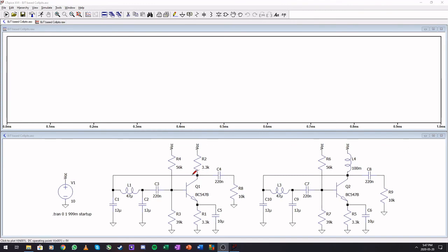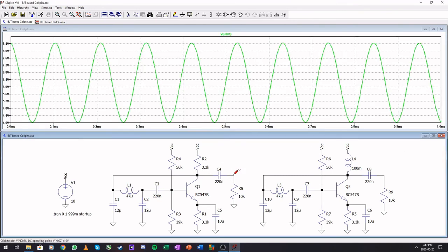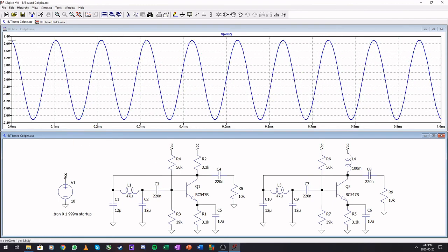There's our simulation done. Let's check our frequency here at the load. And we have a plus minus 4 volt swing, plus minus 2 volts, sorry. And we have about 6 volts available over here, but this is self-limiting itself, and some of these capacitors could be bringing down my amplitude, but this sinusoid kind of looks nice.